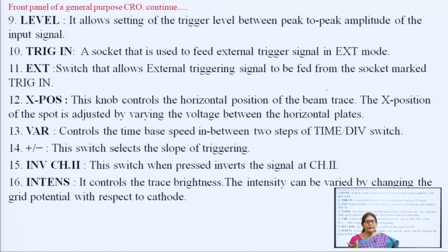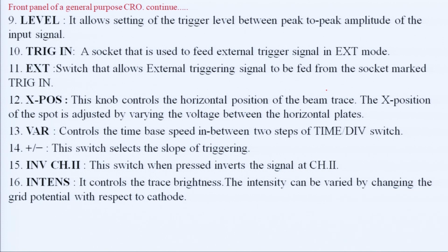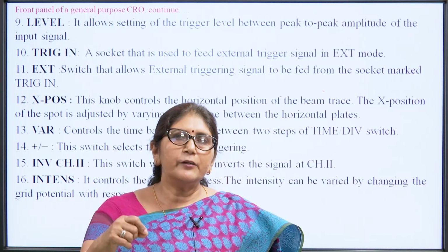Similarly, invert channel 2, I have already told, is used if we want to subtract from channel 1 whatever signal we have applied at channel 1, the signal that is applied at channel 2. Then what we will do? We will invert the signal which is available at channel 2, and then we will subtract channel 2 from channel 1.